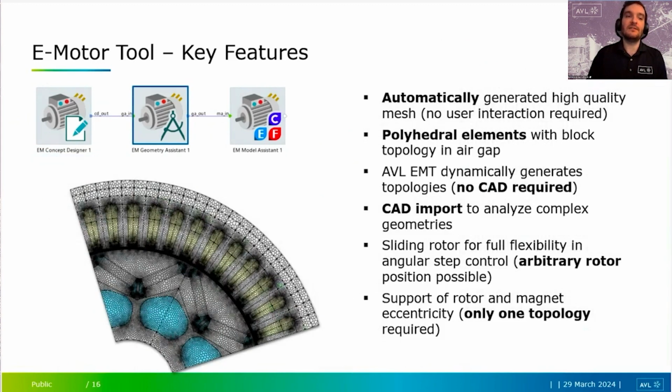And this is where you have your ability to mesh it. You can see now when I'm describing this geometry definition phase, how you can get a drawing of it, and then you can effectively mesh that. So automatically, the tool AVL FireM will mesh the drawing, and it'll do it with the best practices, so you don't have to worry about your mesh sizes and what type of mesh you want to use.